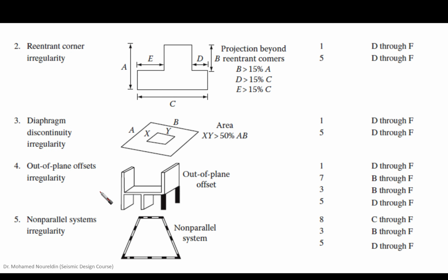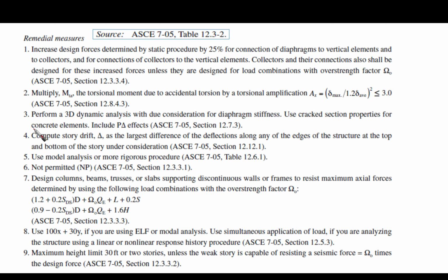As we said, it is going to be extra loading, including overstrength factor. Overstrength factor, as we are going to find later on, is going to increase the design loads for these elements. This means that we are going to make them elastic during the analysis, increasing their design forces, making them huge with sufficient strength, so they are not going to go into the nonlinear range, and we are going to keep them behaving elastically during the earthquake. Okay, did you understand this idea?